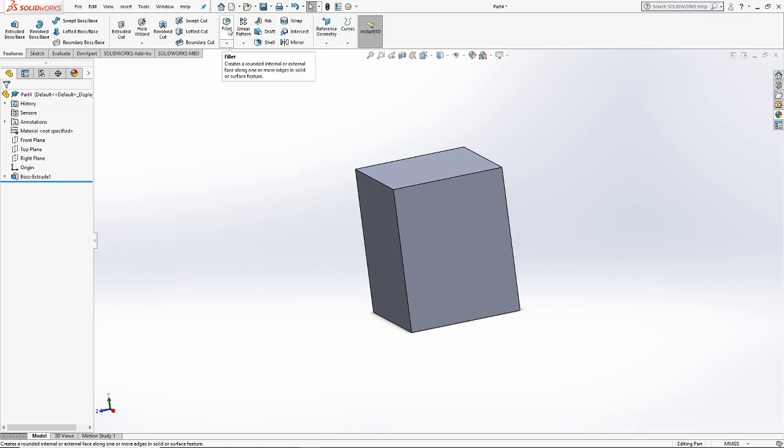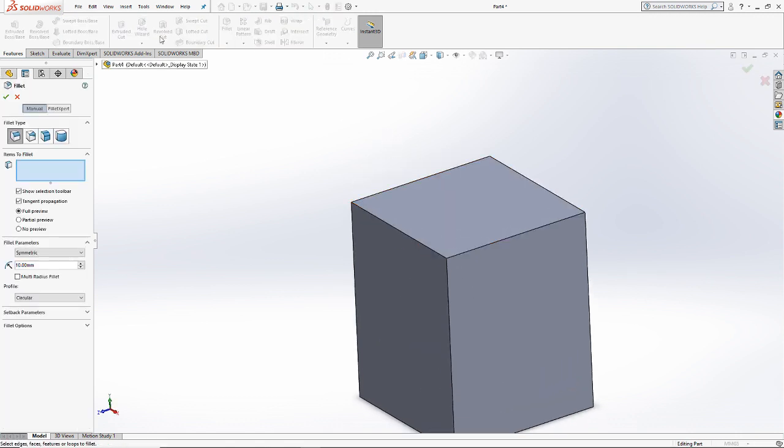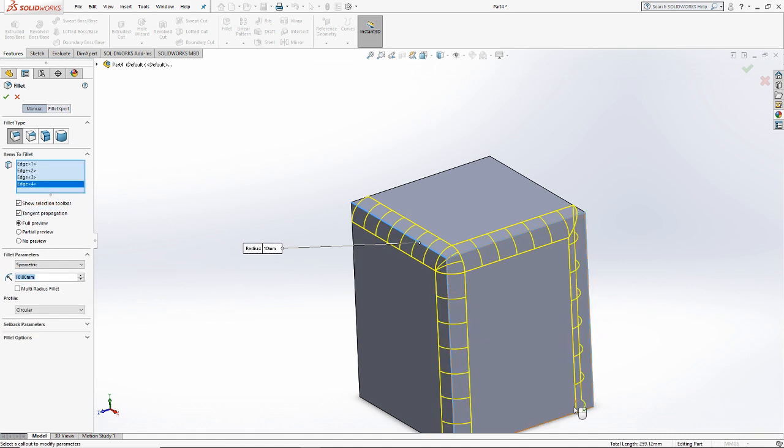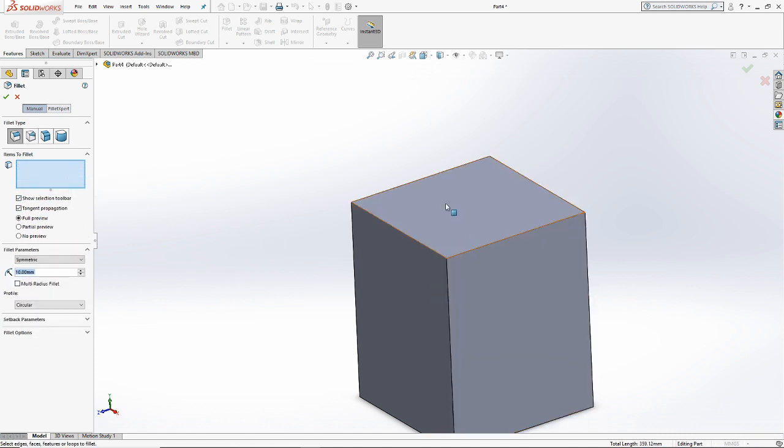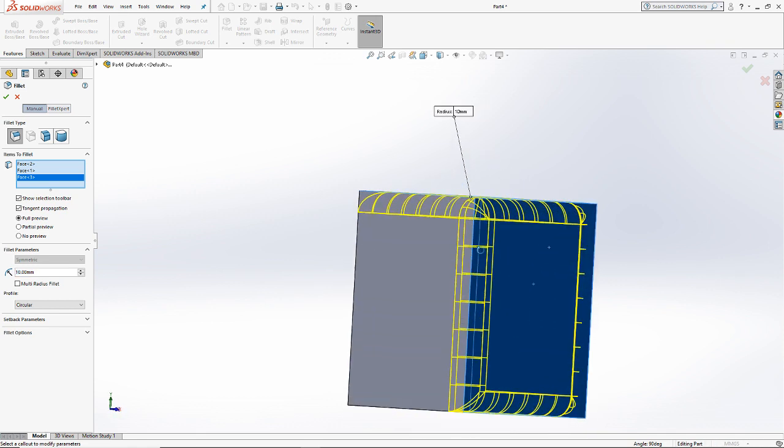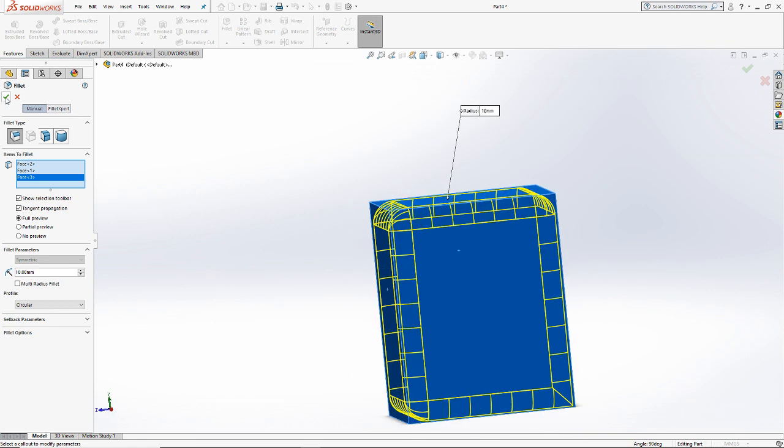Let's think inside the box created by the cube. I want to establish some fillets on the edges. I can do that by using the fillet tool in 3 dimensions and select whatever edges I want to apply fillets to. The fillet tool is also useful for defining fillets on the edges of all faces. If you click on the entire face, you can define those edges.